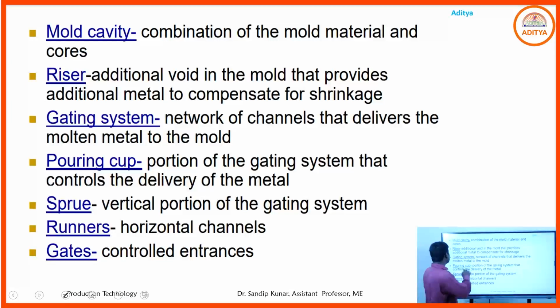That is the use of the riser. The riser is used as a reservoir, an additional void used for storing molten material. When shrinkage occurs in the mold cavity and voids are created, the extra material comes from the reservoir to compensate for those shrinkage voids.